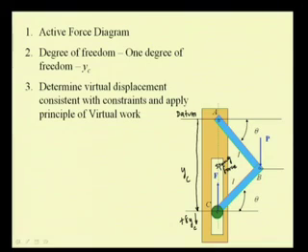If we define this coordinate yc, then the other coordinates, say the coordinate of this point, I can say this is yb, is defined in terms of yc, and this angle also is defined in terms of yc. So, this is clearly a single degree of freedom system where I can specify the coordinate yc in order to completely define the configuration of this system.